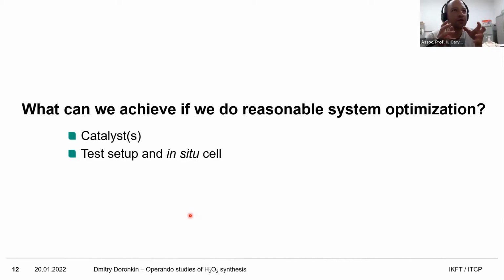Because what you try to do is to combine the yield, yeah, the catalytic yield, with the chemical species. This is what you are trying to do, to find which is the active chemical species of the catalyst. But the chemical composition of the catalyst is changing along the bed. Yes, as the gas composition is changing.